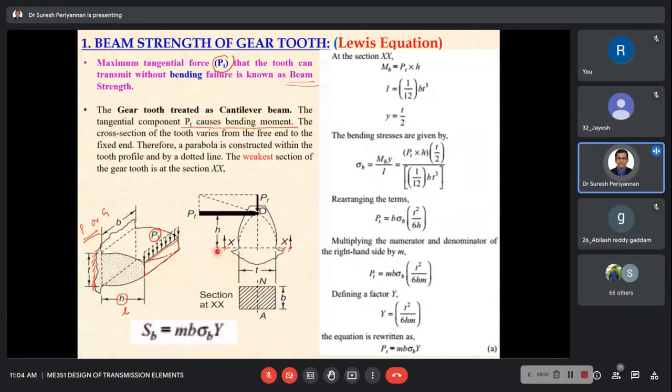Now this is the region of maximum bending moment. Hence we are considering it as the weakest section or region of interest. Because later you may ask, sir, this cross section is varying, a parabola, so how are you considering I equal to bd cubed by 12 for a uniform cross section? Because this is the weakest region, the corresponding dimension is what we consider for our moment of inertia calculation.